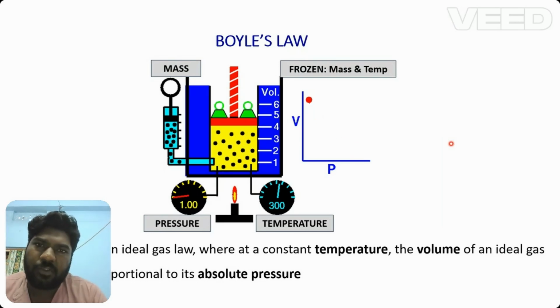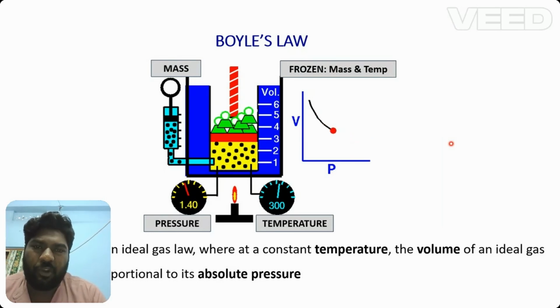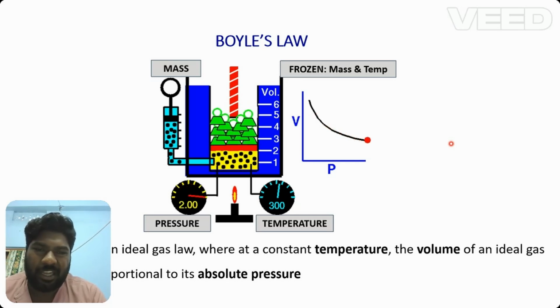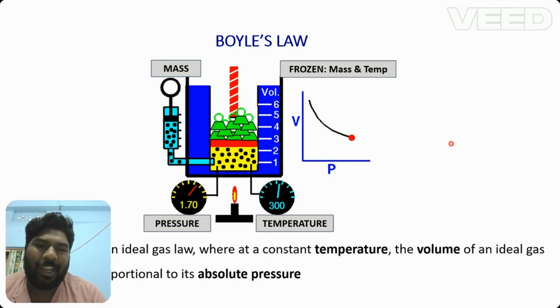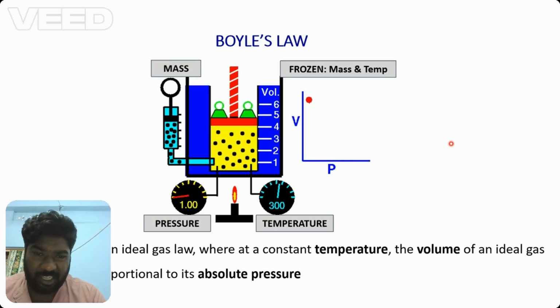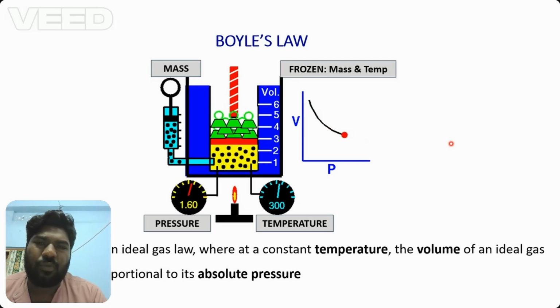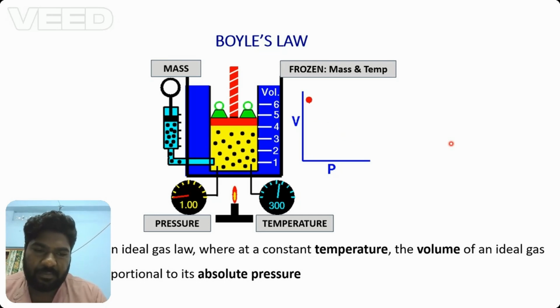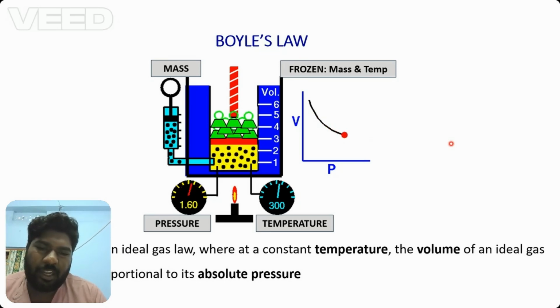Pneumatics works on the principle of Boyle's law. In the graphical presentation you can see that whenever volume decreases, pressure increases, and when pressure decreases, volume increases. We take a fixed amount of space and decrease the volume at a constant temperature.